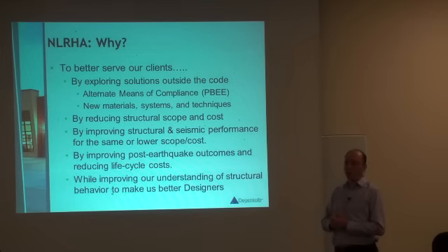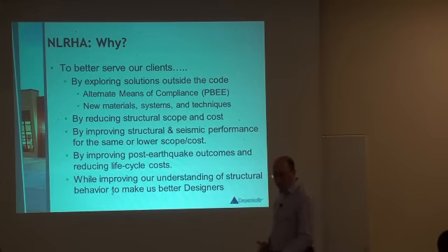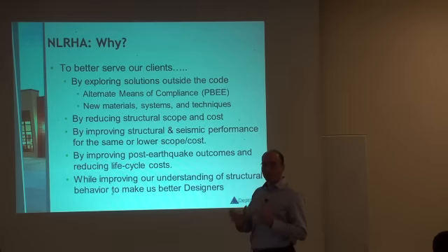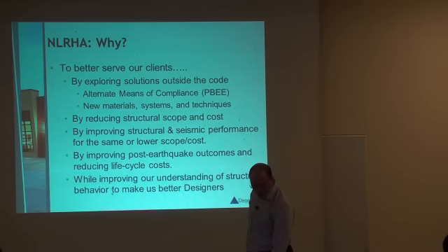Being able to model the building in detail may help us avoid very costly repairs. We want to offer more information about performance-based design. How does a building perform after an earthquake? How much can you limit the drift? Can you limit the non-structural damage, say for a hospital? And this also falls under reducing life cycle cost.